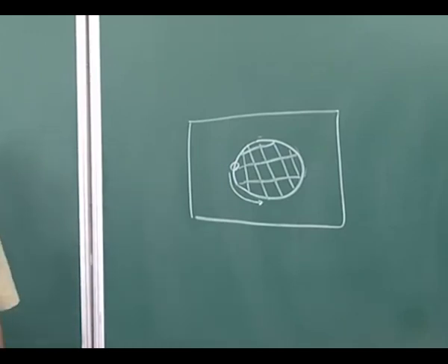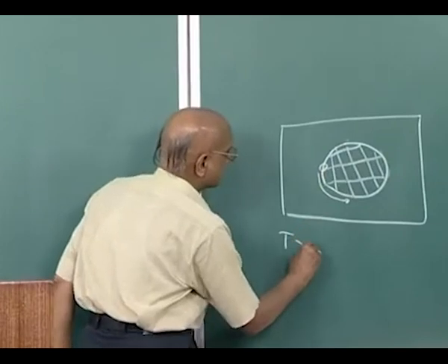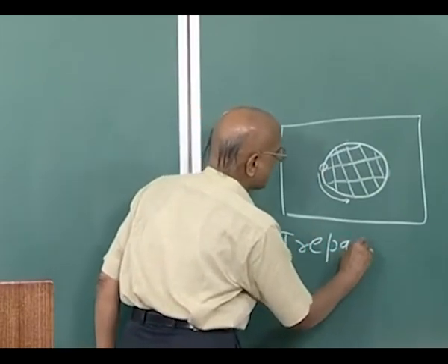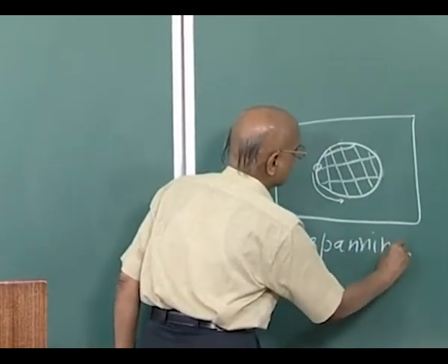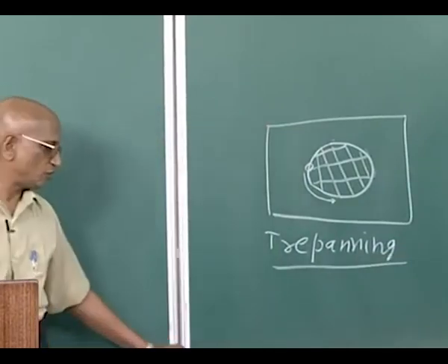But normally electron beam machining is not used for very thick workpieces. So for even thin workpieces, you can use this trepanning operation for making larger sized holes rather than melting and vaporizing the whole of the workpiece material. This way the CNC feature is very useful for creating different kinds of features on the workpiece surface.